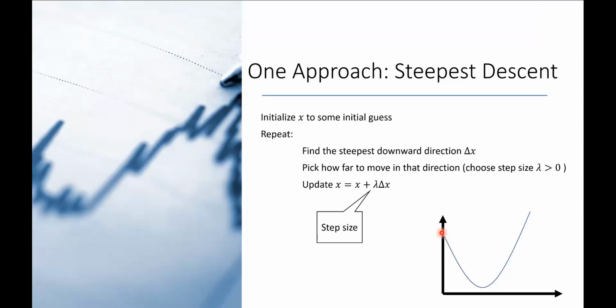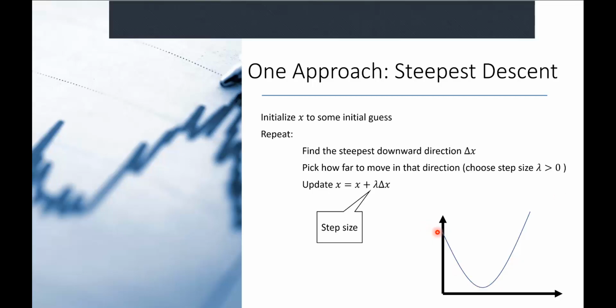My goal is to figure out which direction do I move, say, my joints to minimize my error, right? So the steepest downward direction for my error function, which might be this bowl-shaped thing here. So if I take the derivative at my current position, then I get the slope, right? So I get this linear approximation of my function at this current point. And then I can just follow that downwards. That's going to tell me which way is up, which way is down. So I can just follow that down.